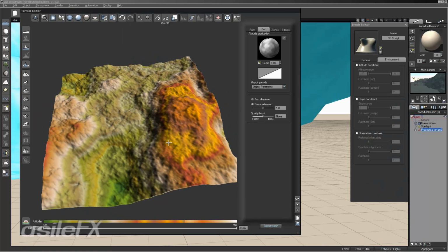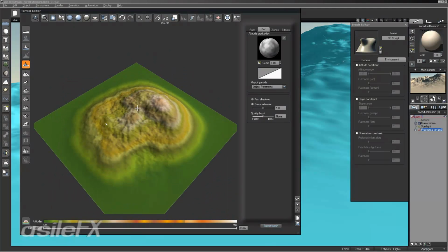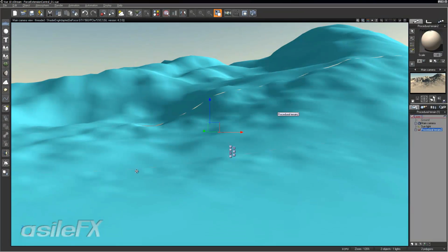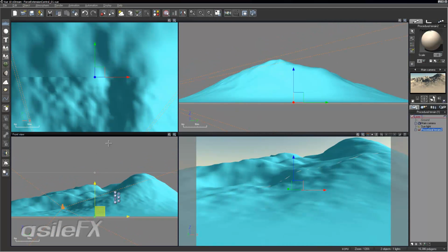So about 0.4. And I can turn back on 0 edges if we want to have that on. And now that clipping and cutout on the bottom is gone. Another thing you'll notice is because our bounding box fits correctly all the way to the height, our actual scale output for the Z is now going to be correct.